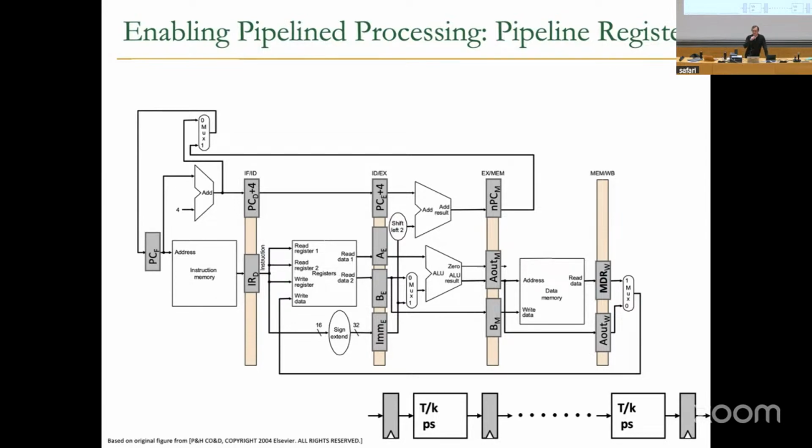Yes? Is it not problematic that this muxer in the end goes back to the register file? So is it not problematic, this mux? It's not actually. That it goes back into the register file, there might be something else in the pipeline. That's true. So we're going to talk about that. If that something else is not reading that register, it's not problematic. So what does this mux do? Let's take a look at it.